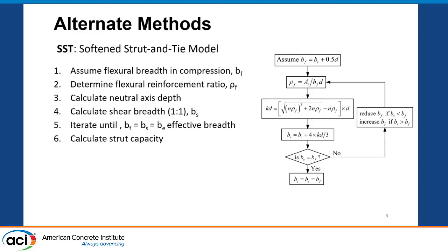But that strut capacity, the area of the strut, is going to be kd, which is your depth, times your effective breadth. You just calculate this, and you're going to have an inclination angle associated with that. So again, area based on d and b_e converged. You're also going to include softening factors here. One of these factors is proportional to the concrete compressive strength. The other factor is proportional to the inclination angle of the strut. And that inclination angle runs back to sort of the centroid of the stress distribution of the top portion in compression. It'll be much clearer on the next slide, but words first.